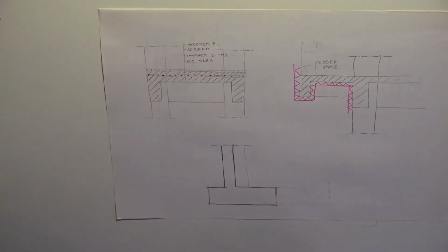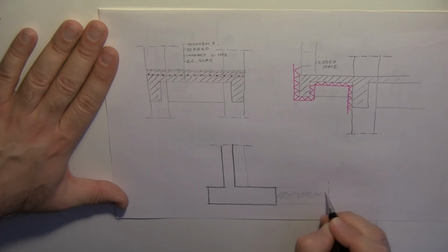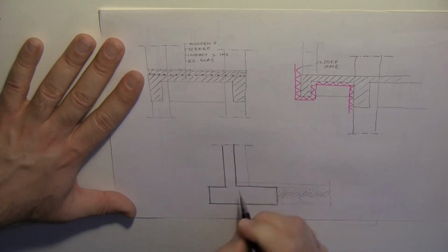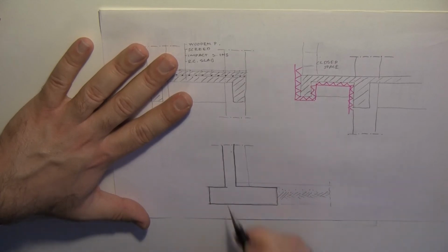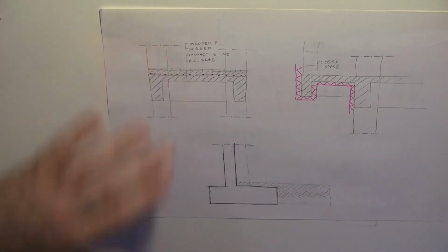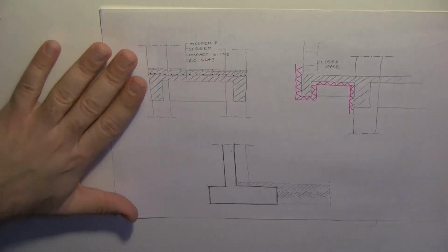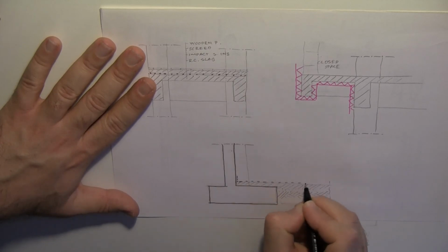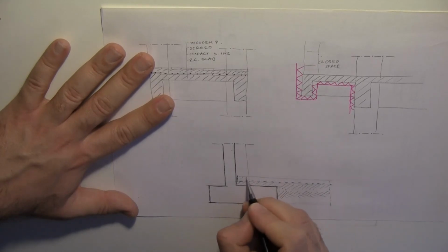Now what I will do is I am going to compact soil here. And I'm going to lay gravel, and I'm going to cast the, maybe let's erase this line and transform it into a dashed line. I will have here a slab. And in order to make it damp proof, what I can do is place a damp proof material or waterproof material here, and I can cover it with screed.